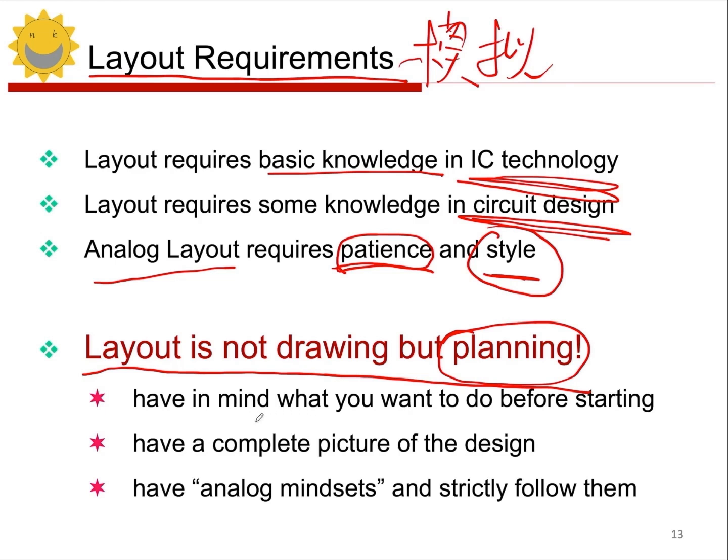Before drawing, think about what you will create. Have a clear idea of the layout. Plan the layout in your mind, considering which components match or need isolation. Preliminary planning is essential. Drawing without a plan makes it hard to achieve a good layout. Start with a clear plan. Sketch rough drafts on paper before drawing the layout.